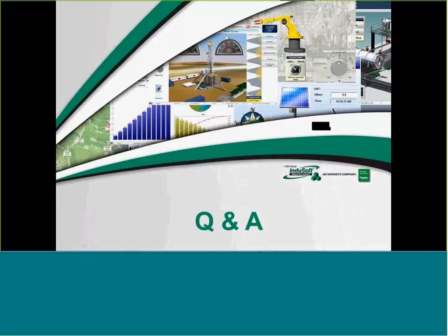If the user is asking for a SYSMAC NJ product, one of the things that I've developed as an Omron engineering tool, I have an Excel worksheet where you can copy and paste the tags out of our SYSMAC Studio software product, paste them into Excel, click a button, and it massages and builds a driver worksheet that you can then copy and paste directly into InduSoft Web Studio. So that's something that we can make available.